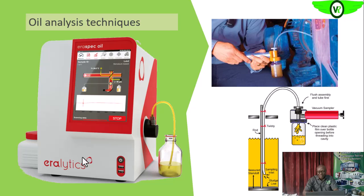And then secondly, you see, like this hand pump, this tube is connected through the sampling point, or sampling hole, into the sump where we have the oil. It is also very important that you do not allow the tube to get to the base so that it does not pick up sludge from the oil.